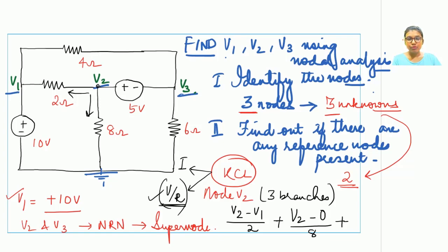So it is assumed to be at a higher potential. Our direction of writing the equation is from left to right. So we start with V2. When we are traversing from left to right, what is the last sign encountered for this 5 volts? It is minus. So it will carry a minus sign.